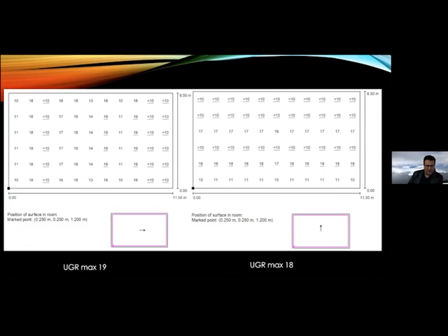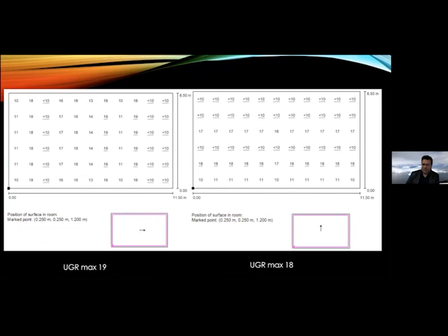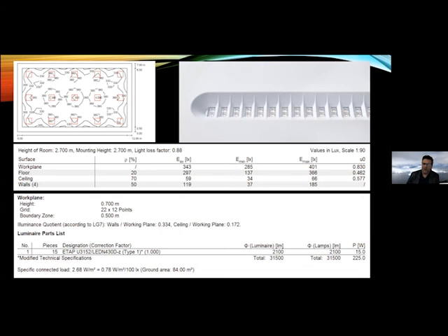In terms of glare, you know, glare is another story. But if you look into the glare of this particular model, and if you select a luminaire for our market, you can expect a well-controlled glare too, with UGR values maximum of 19. The glare of the luminaires coming with this kind of optics is a completely different chapter. Probably I will be happy to talk about it at the next opportunity.